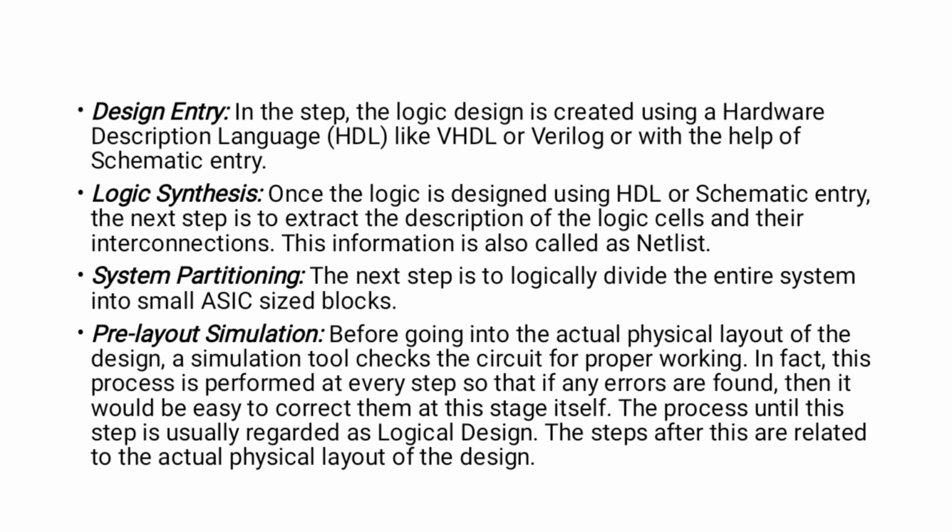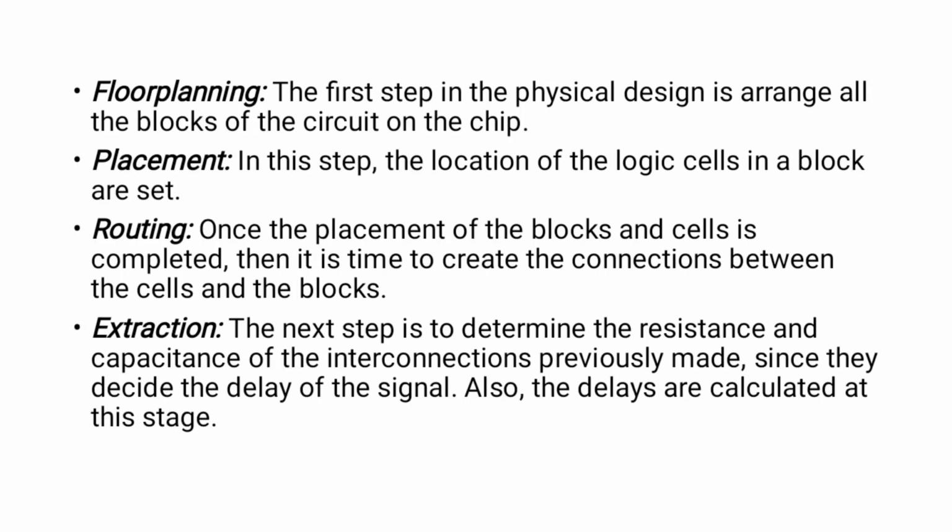In design entry, the logic design is created using a hardware description language, and logic synthesis converts it to your netlist. System partitioning logically divides the entire system into small ASIC-size blocks. Before going to the actual physical layout, the tools check the circuit for proper working logically; that is pre-layout simulation. In floor planning, the physical design arranges all the blocks of the circuit on the chip. Placement tells about the location of the logic cells in the block or set. Routing, once placement is done, creates the connections among the cells.